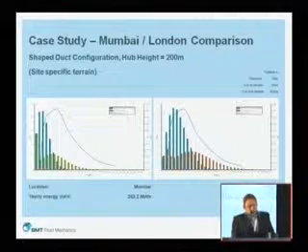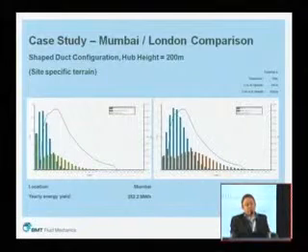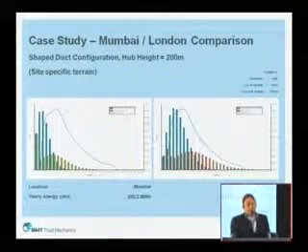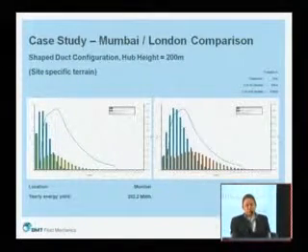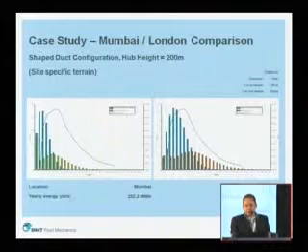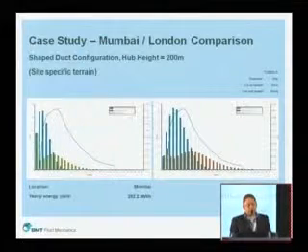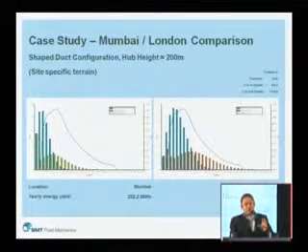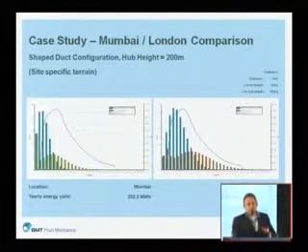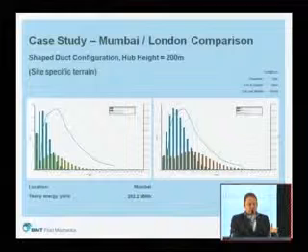The point of this slide: this shows two different locations. We have considered a 35-meter diameter turbine placed some 200 meters in the air, and considered London and Mumbai. London is on average much windier than Mumbai, so for a given turbine it would produce a lot more wind energy yield. So the point of that really is that something that works in one location doesn't necessarily work in another location, and therefore these are really bespoke design solutions.